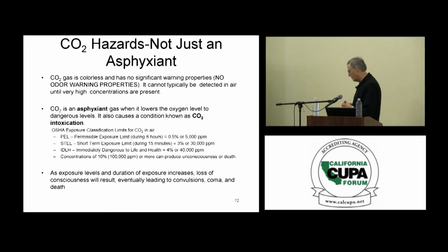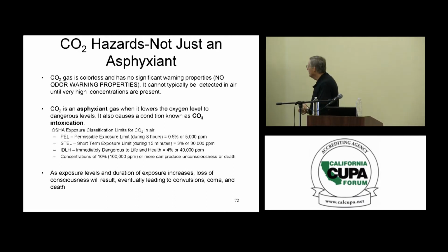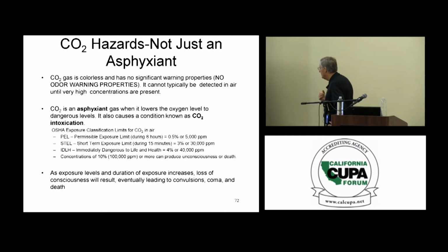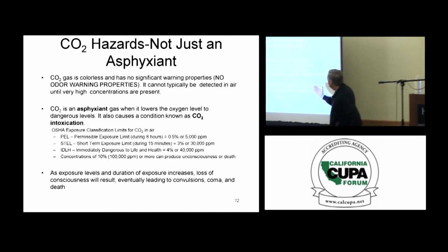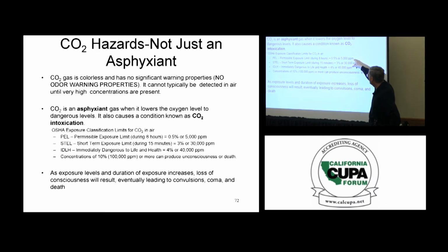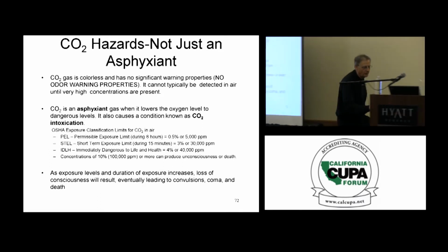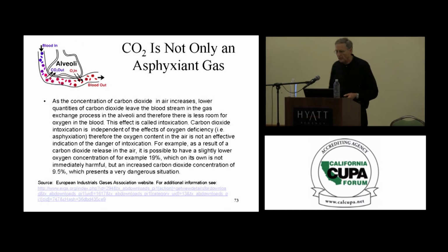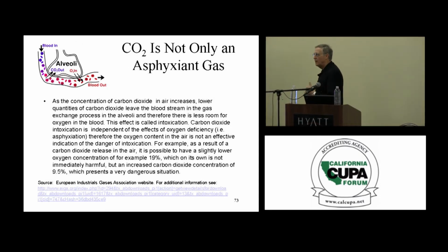Okay, and CO2 is not just a simple asphyxiant. If you have CO2 releases into the workplace, you could have a release that causes the oxygen concentration to drop to, say, 19%, which is not highly hazardous. You're starting to get in the dangerous zone. But those kinds of concentrations would be over 5,000 parts per million, to be close to 10. And so CO2 has a particular characteristic because when you inhale and exhale, what happens in your lungs? You have gas exchange.